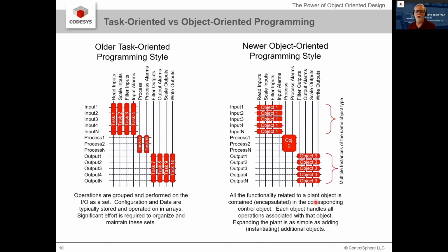For instance, in a task-based approach, the control design is completed first, then the alarm manager is added, and then the persistence manager is added, and then the log manager is added, and then the visualization is added, and so forth and so on. And if you ever have to add something, if you add another input, or some more functionality you need to add, you've got to go back and add it to all those lists before you're done. And hopefully you don't forget, because it's a very easy thing to forget.